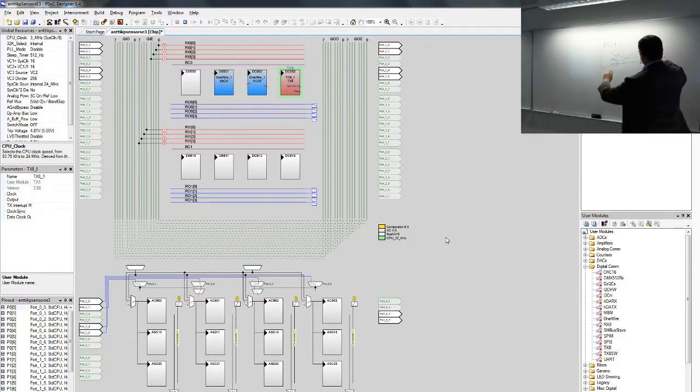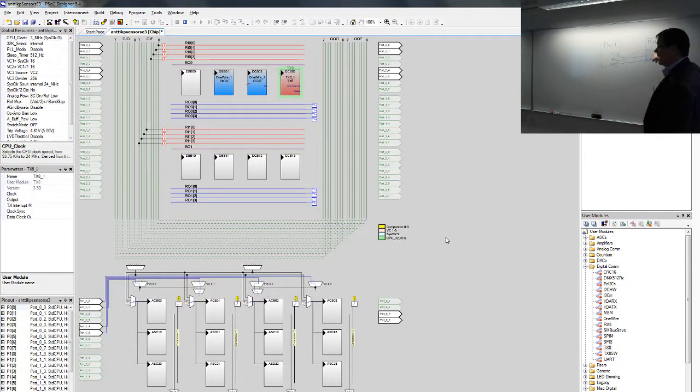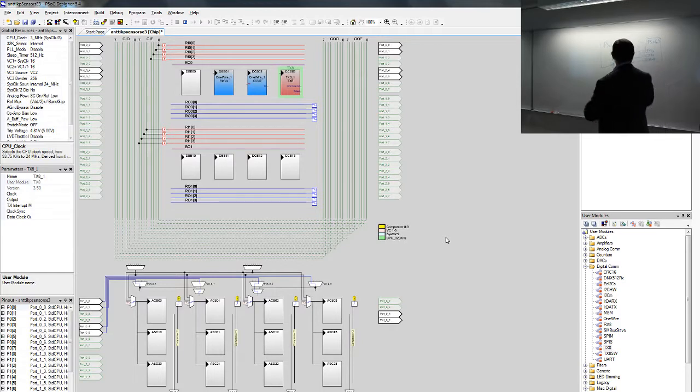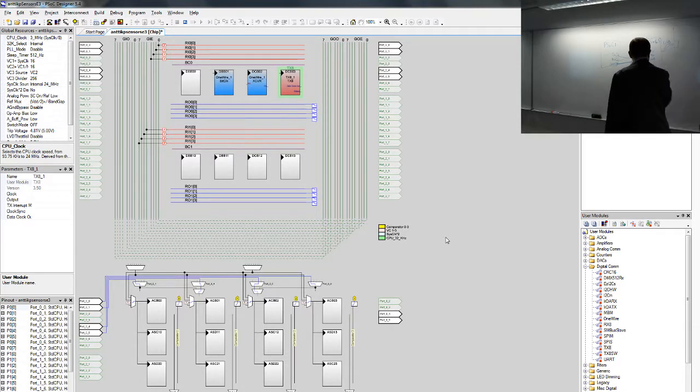A common mistake is to have the straight lines there, which would be how a bridge should operate. So the bridge is a modem kind of device. And if it doesn't start working like that, then try the other way around. Okay, all right. But anyways, the wiring, without this ground wire, absolutely no guarantees that it would work, because they basically need to be connected on the same ground at some point. This one basically connects to the PC, the USB port. So that's the USB, and so does the other one too.